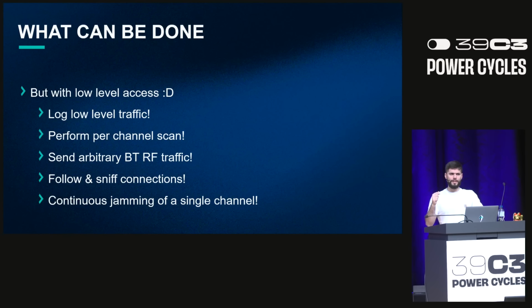Also, because of the RF modes, we could continually jump one single channel. This is very helpful if we want to perform some kind of Bluetooth attacks in the real world, because, for example, we can force one channel to not be used, and then we know, for example, that that traffic can be in another advertisement channel and listen to those other advertisement channels.